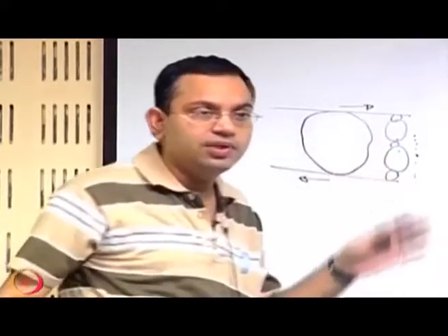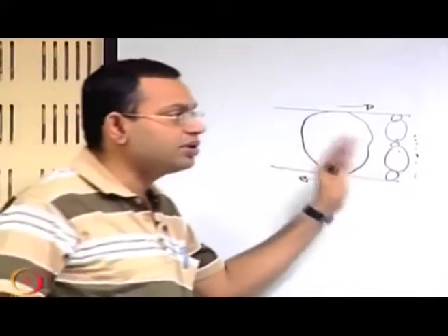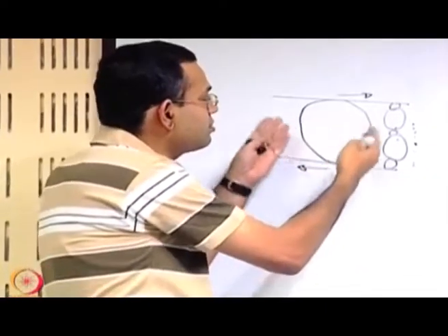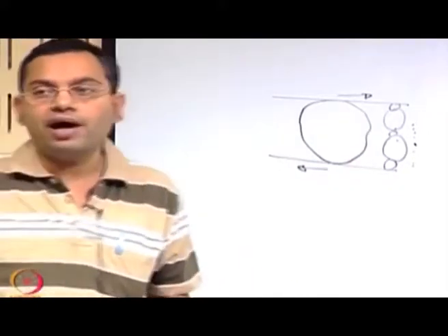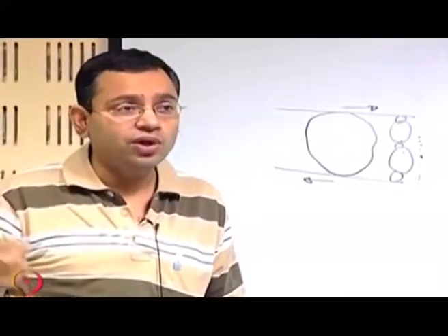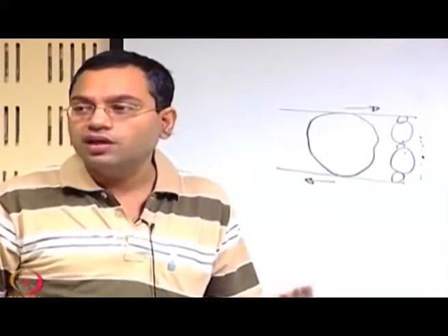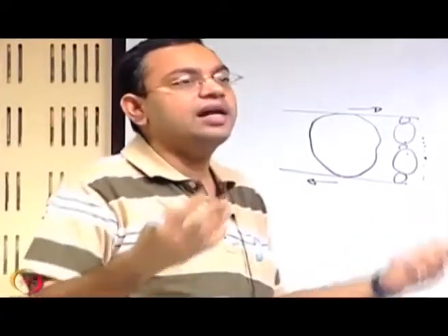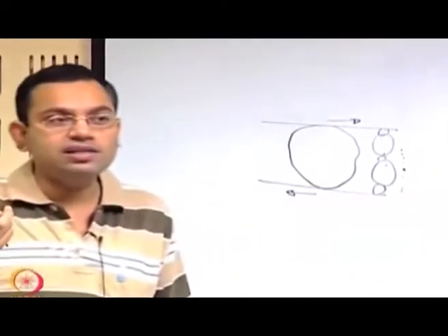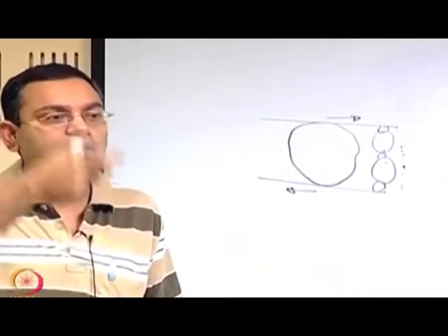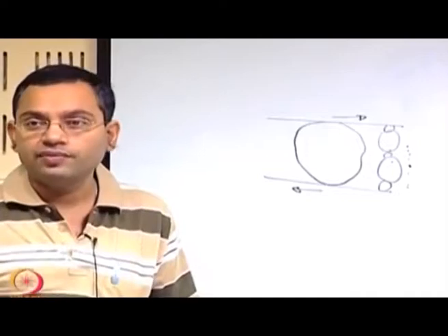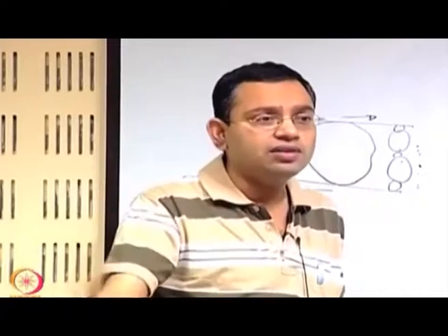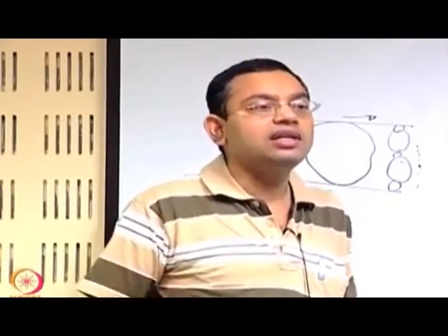Something equivalent is happening in a turbulent flow. This large piece of stone is like a large fluid mass, and it is extracting energy from the mean flow. Turbulent flows are often characterized by high Reynolds number, and that is why they can have a high mean kinetic energy, so that the large eddies can continuously extract kinetic energy from the mean flow and sustain their rotationality. The question is, when the large eddy passes on its energy to the smaller eddy, how does the large eddy itself sustain?